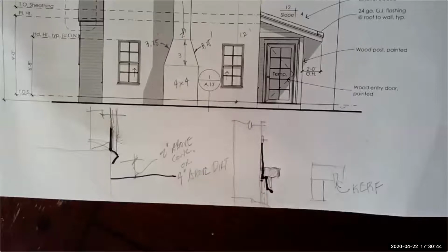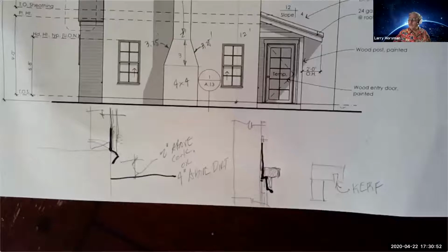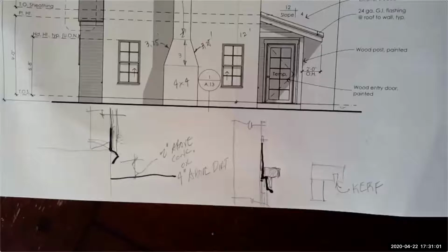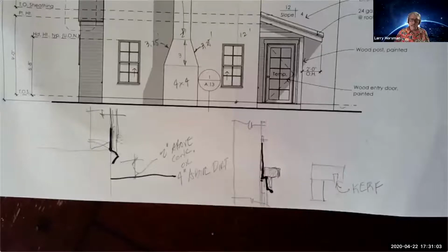Larry, quick question. Is there a difference between residential and commercial for the stucco? Not for stucco. It's the same thing. There are a bunch of proprietary systems because there's a bunch of fake stucco, like Power Wall, and EIFS, which looks kind of like stucco, where they put foam and then just a thin cementitious layer. They typically take the foam, and there's some fiberglass mesh that goes over it, and then a real thin coat over that. But we can take a look at both.